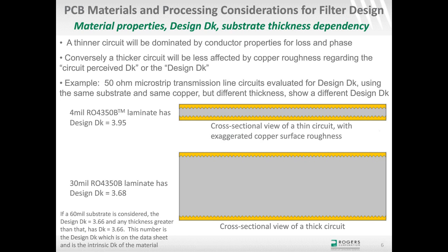This is not effective Dk now. This is actually design Dk, or the dielectric constant as the circuit would perceive it. I get a dielectric constant of about 3.95 on the thin circuits, and on the thicker circuits, about 3.68.